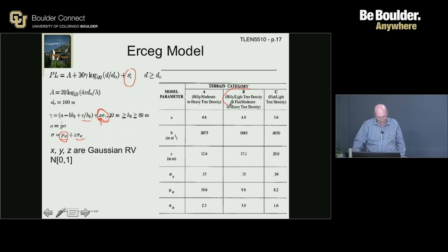What happens? Well, let's look at gamma. I mean, we can look at everything, but they give you the parameters for everything, which allows you to plug into that simple model, and more than just a 2-slope model, you know, free space up to a certain distance, and then a gamma slope model. It gives you a little more hint based on the variability and the standard deviation.